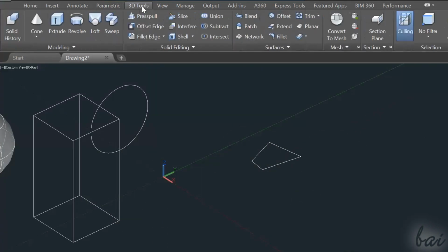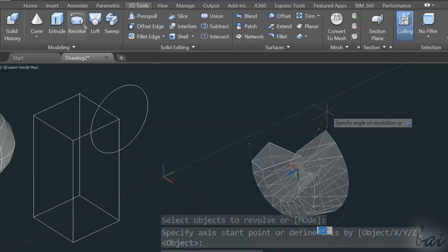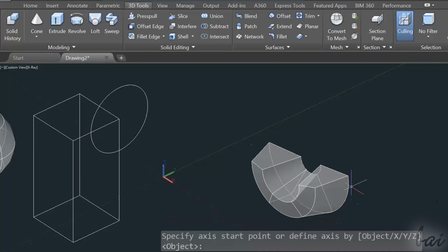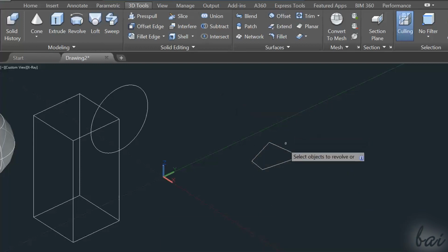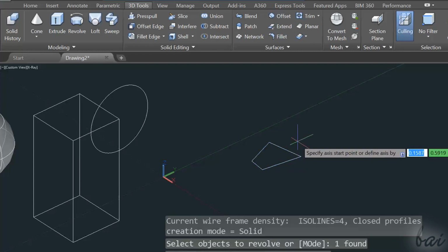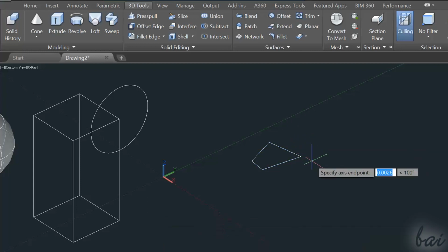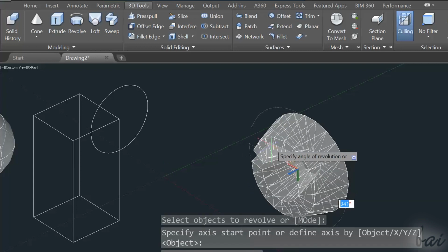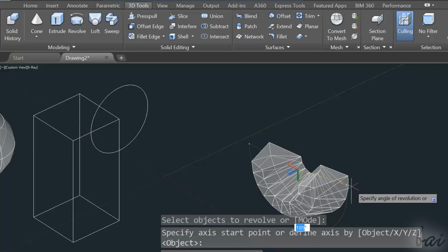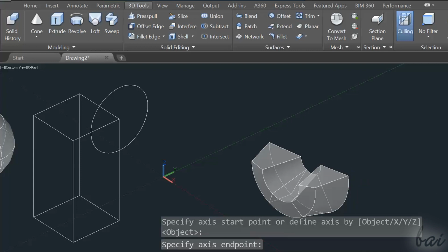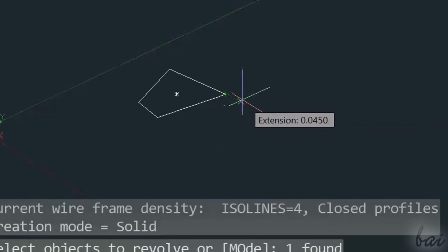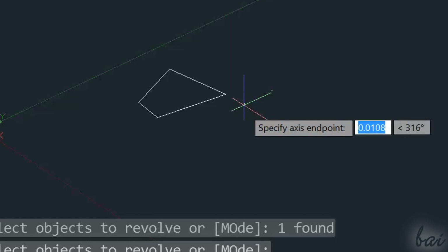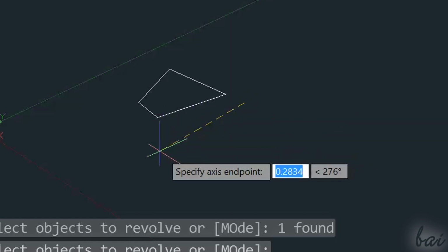The third tool is called the Revolve and creates a 3D object starting from a 2D base. Differently from the Extrude tool, where you define the height to extrude, in this case you define an axis by fixing 2 points and then rotate as you like. In order to make the tool work, make sure to fix the axis outside the base itself and on its same plane.